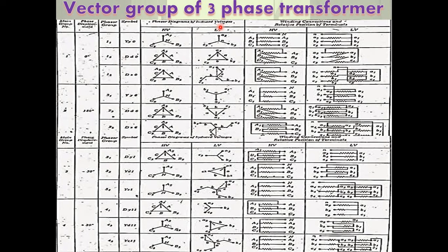Next is star-delta, Dy or Yd. Its salient aspect is that it is very common for supply networks, with one star point for a neutral to serve mixed single-phase and three-phase loads. The delta winding can carry triplen current and so stabilize the star point voltages.